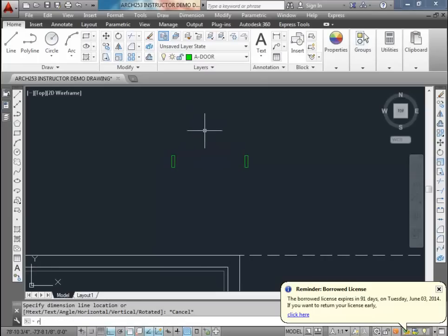And now I'm going to draw my slab, so I'll use a rectangle here. I might as well start it in the center point here and just work my way backwards. So this is going to be at -1.5, -36, so there's 3 feet. Okay, so that's my door slab, and now I'm going to actually do an arc.